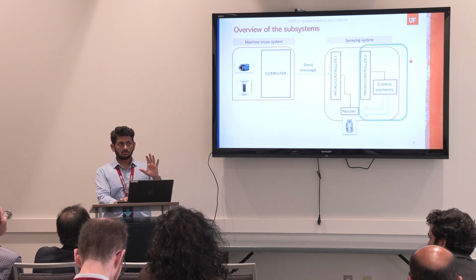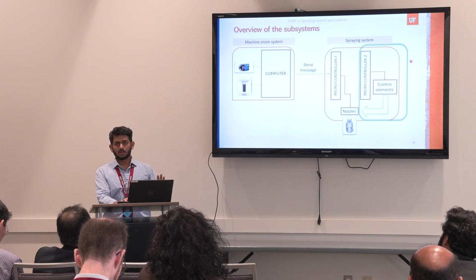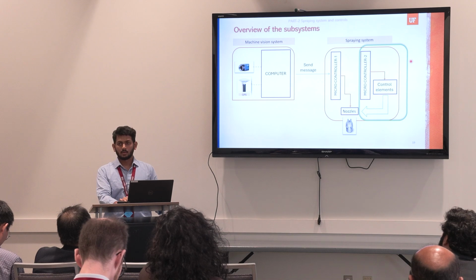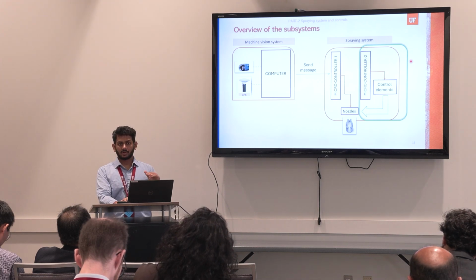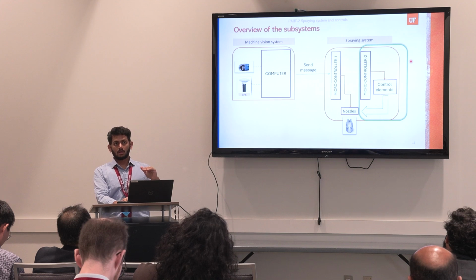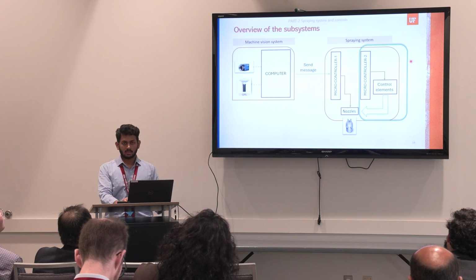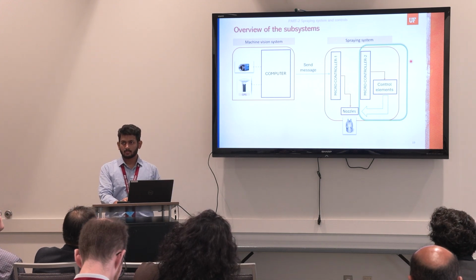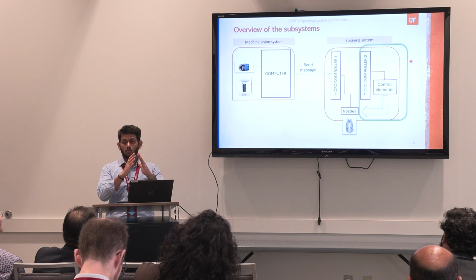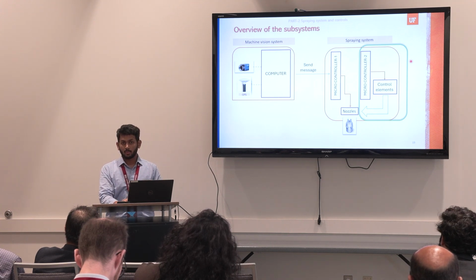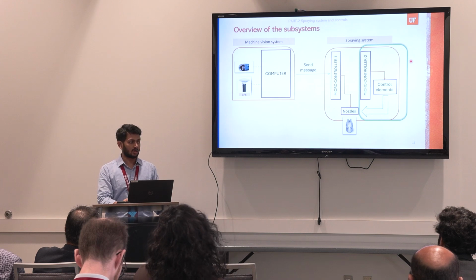A few tests were done based on the nozzle height, the number of nozzles, the types of nozzles, as well as the pressure, and based on that we found that between 15 to 20 psi we get a good spray which is less wide. We don't want a large cone angle, we want a narrow cone angle, and we also want to maintain the pressure so that it is not affected by drift.